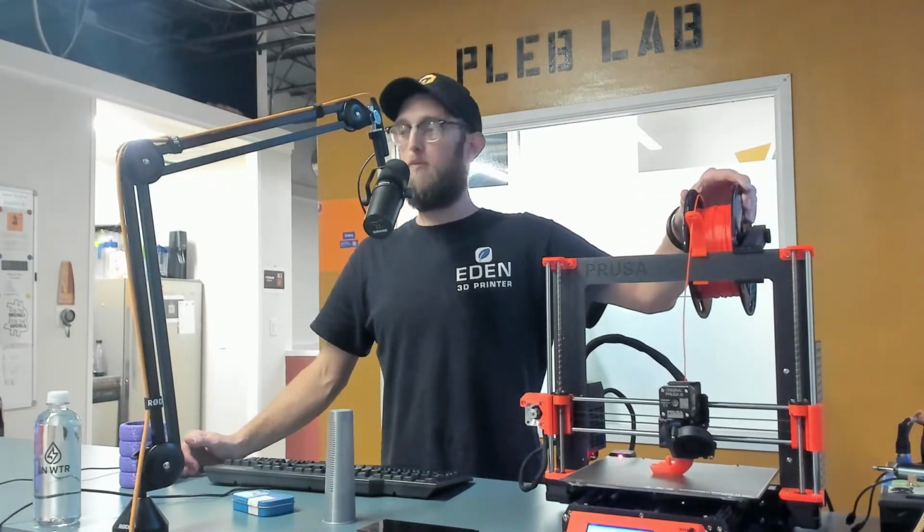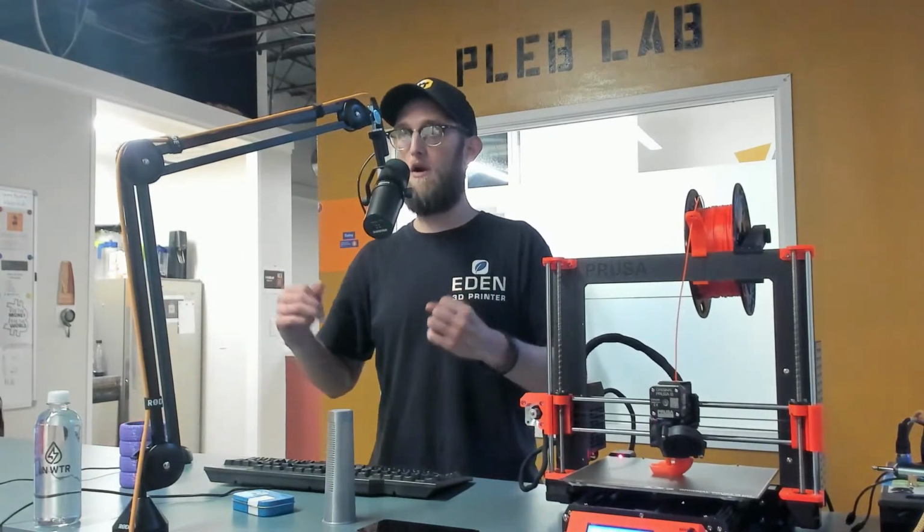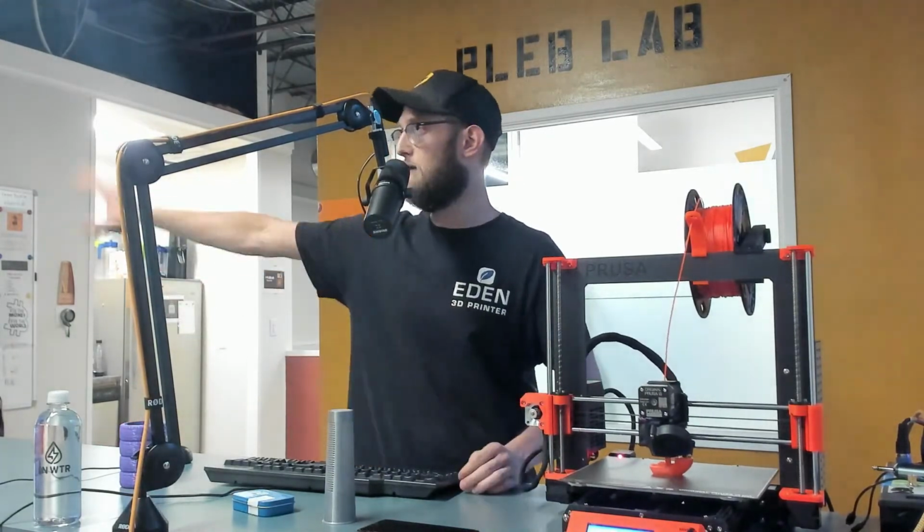Plastic sitting on a spool, just on a table for more than a couple days will soak up water. It's hygroscopic, so it's going to attract water. Different materials, we didn't even get into the different types of materials, will absorb water at different rates. So it's really helpful for your printing quality. Say the machine is calibrated perfectly. Say you can guarantee that the slice worked.